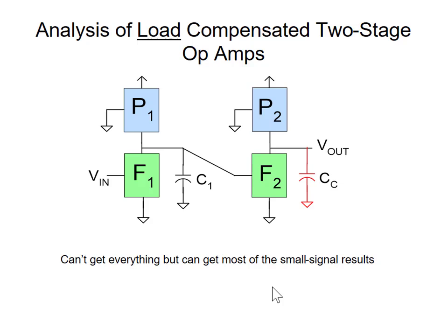Okay? So which one we determined to be the high frequency and which one is low frequency? We've assumed that it was internally compensated. So the capacitor C1 in the previous analysis was a big capacitor. That's the low frequency pole. How about this structure here?